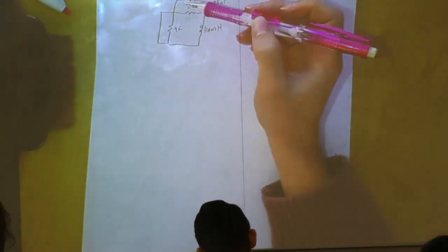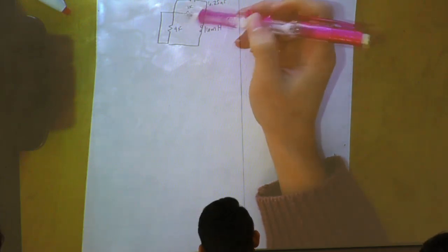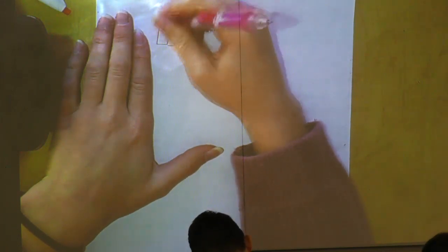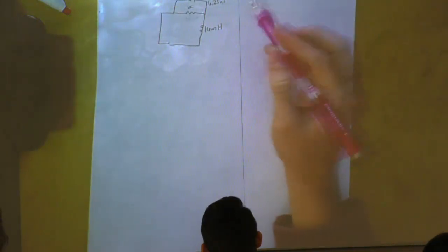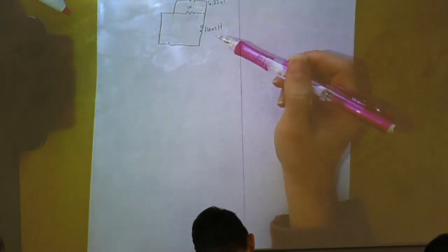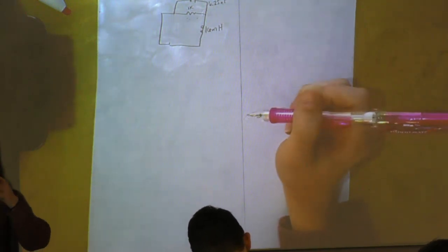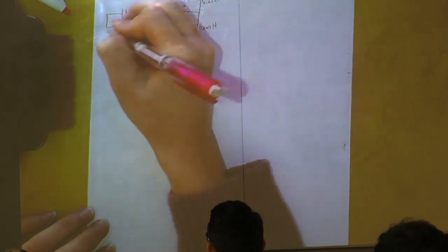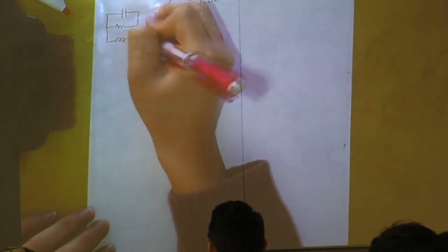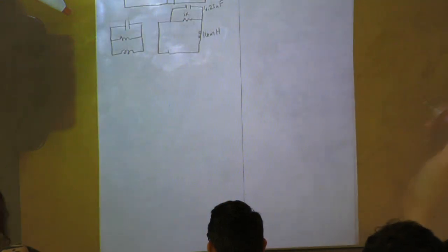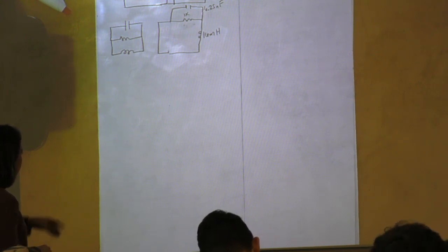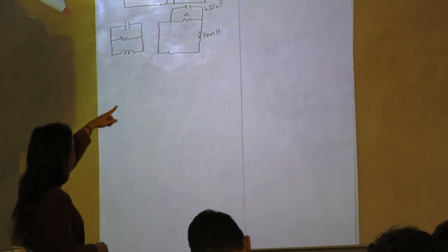So our 4K is in parallel with a short. It's going to get canceled out, so we'll just erase it, and we can see that our circuit is in parallel. Does anyone have any questions about how it's in parallel? We have our capacitor, our resistor, and our inductor. This is at 0 minus, 0 plus, because at t equals 0, we close to B.